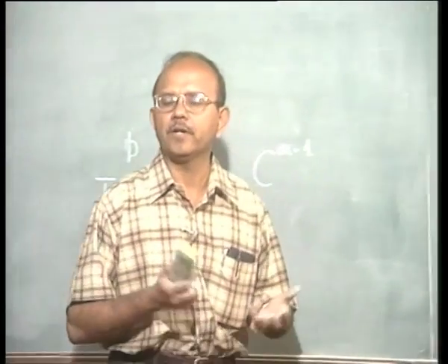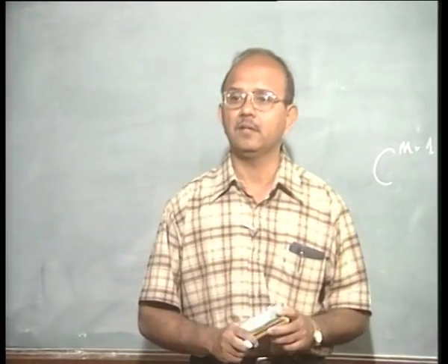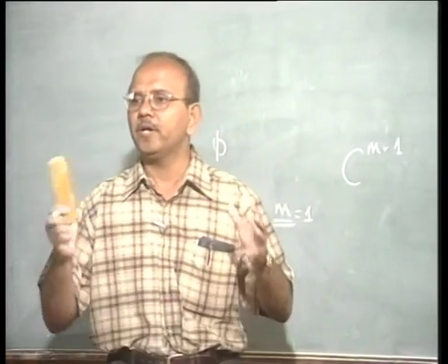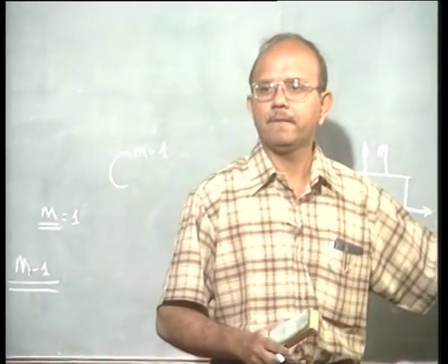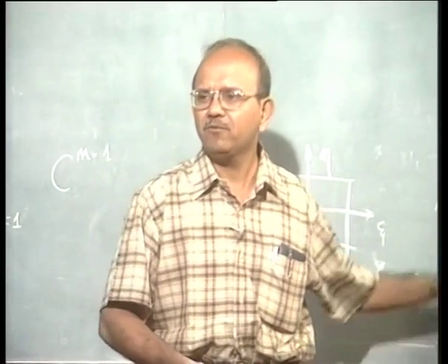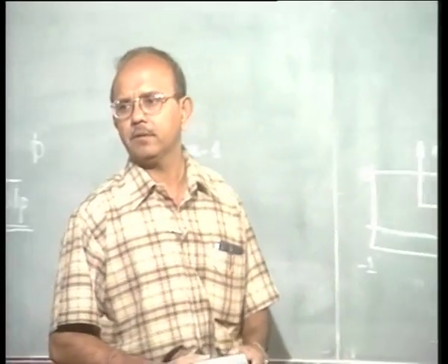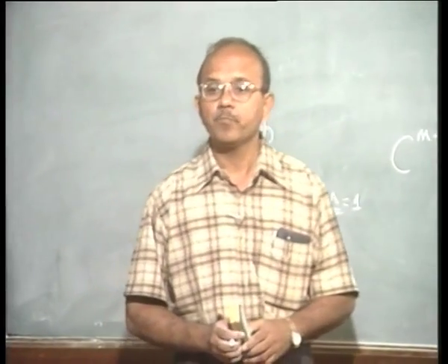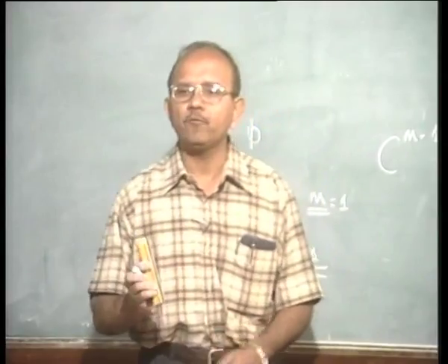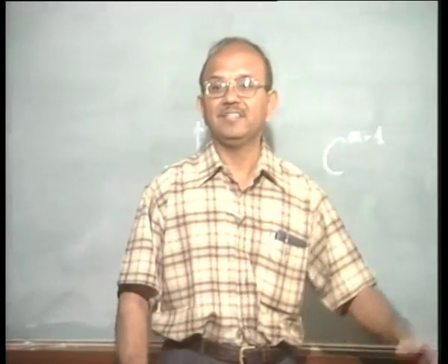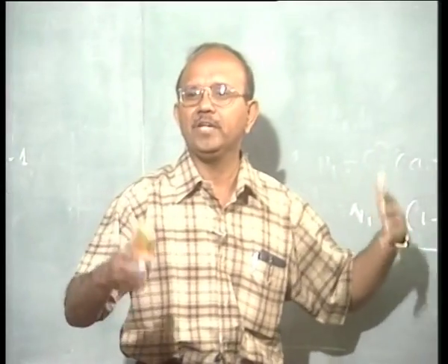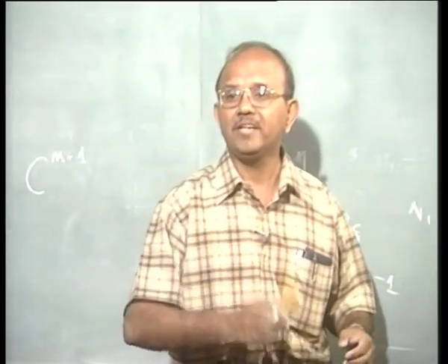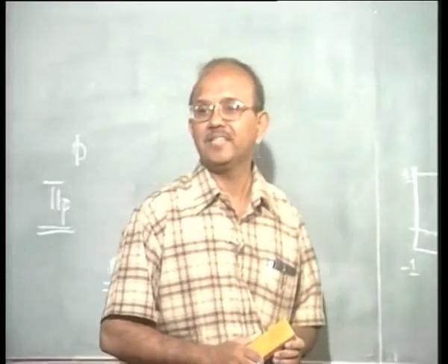Obviously, when I go to very complicated geometry, I won't be able to fill up that geometry with such nice shapes. When I have automatic mesh generation, I have no control over exactly the shape of the elements. Number 2, you have been interpolating only the field variables, phi, or in other words u, v and so on, but you have not interpolated the shape.